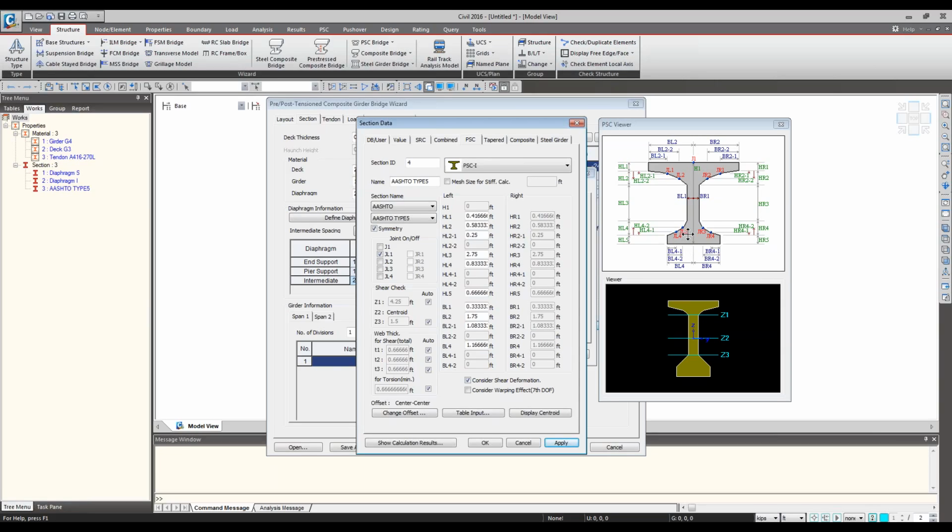Or for the pier, above the pier, for the concrete pour, if the bottom flange needs to be thicker, you can freely modify that any way you need. So from 0.6 to 0.5, I could increase my flange thickness like this. So this way you can freely manipulate the section based on the database.